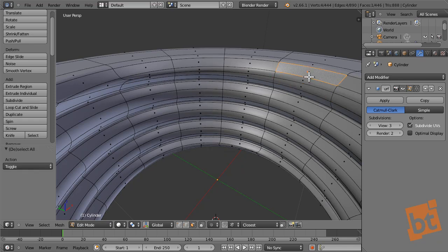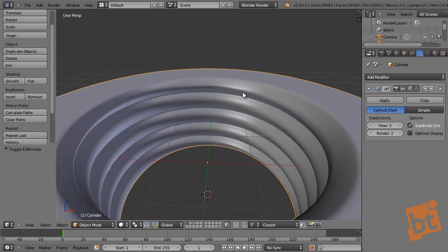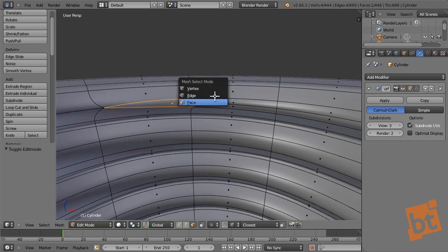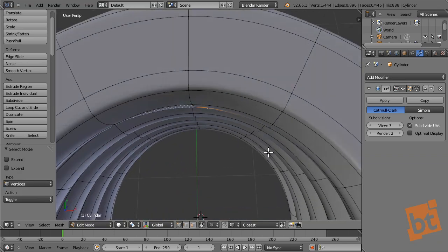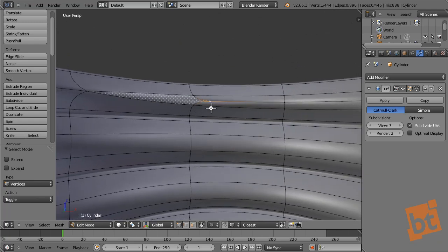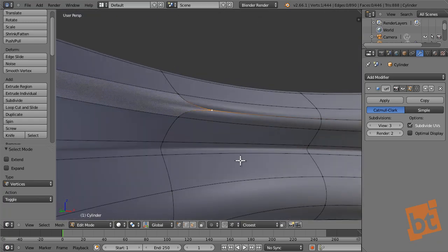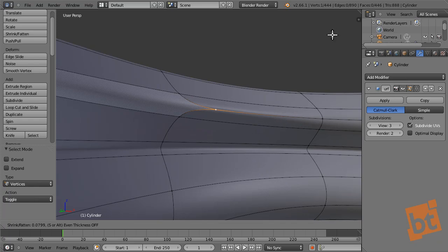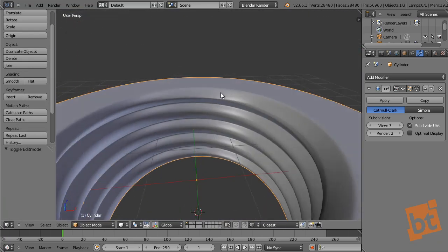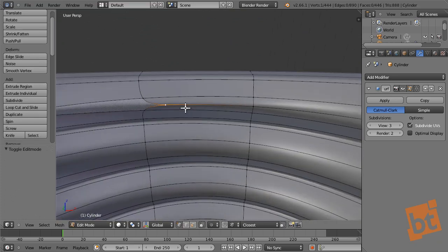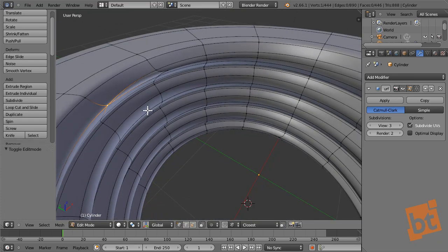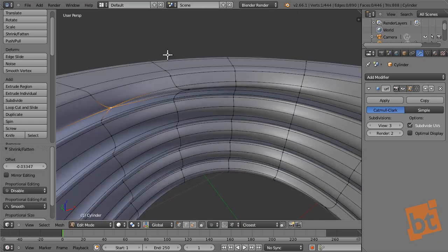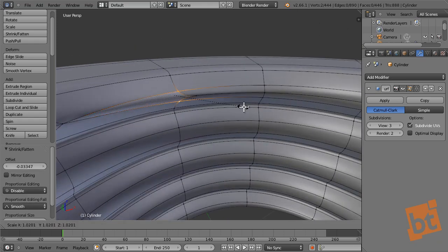So now, as you can see, we have two quads here, sorry, and another quad here. And we had that there because this vertex here is making a little weird shape. So we can get closer, and with Alt S, we can move something into the normal. So something like this probably. Okay, this looks much better. That's some kind of a pinch, right? So we can arrange this by moving a little these ones. Here, maybe scaling this too a little.